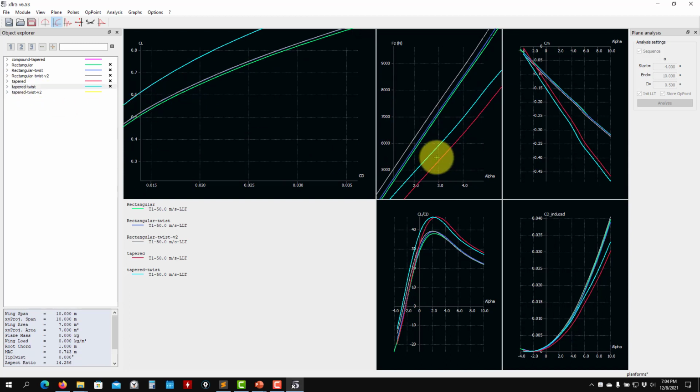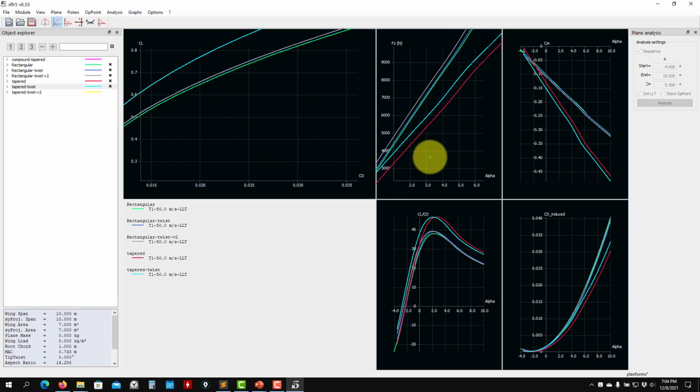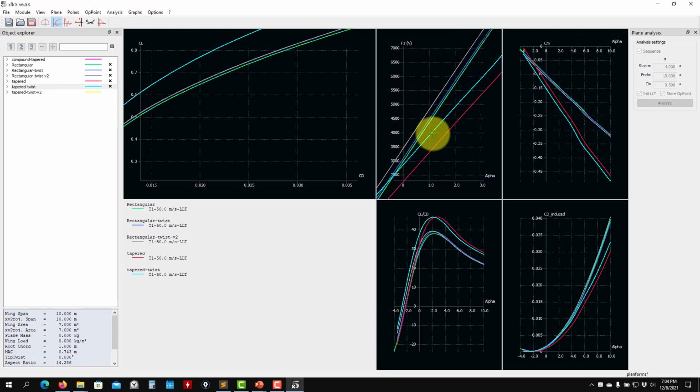So it's a much better result than the red one with washout at the base. In this case for 4000, see that we improve it a lot by adding that twist. So now about 1 degree, this is a very good cruise condition, and close to this one. And see that very small differences in angle of attack are required, like 0.5, 0.8 to reach those conditions. It's strange when you need to do something from 0 to 3, it's very strange. And this is what we have.